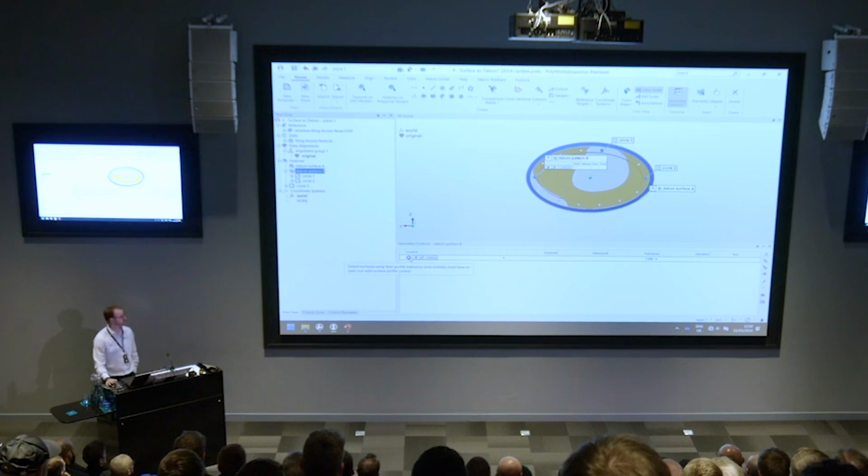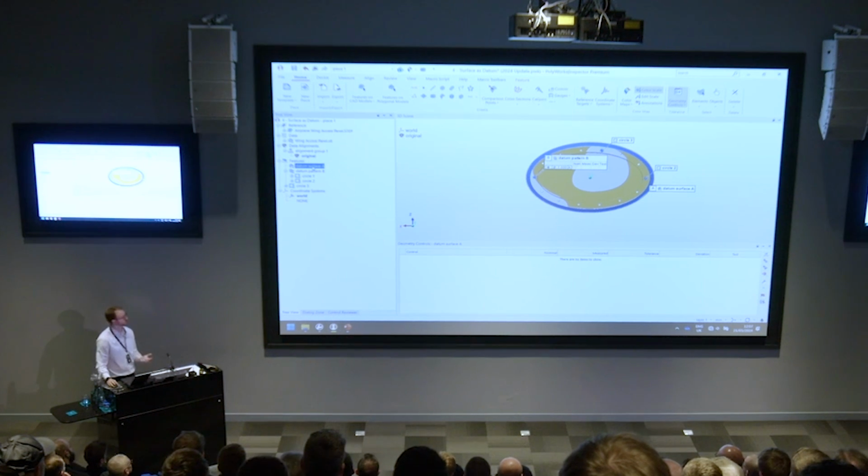The good thing about PolyWorks is that a lot of the errors that you will see, they're pretty good at explaining what the problem is. So you'll see there that the datum surfaces using profile tolerance, tolerance zone mobility must have at least one valid surface profile. So obviously I've not applied that just yet. So if we jump into the datum surface A, again into the geometry controls, I can add a surface profile.